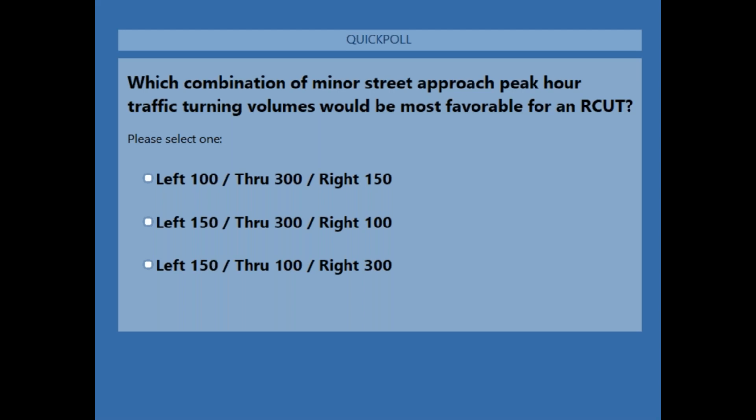So for example, and again, if we're dealing with a slow moving piece of farm equipment, unlike a vehicle or a car that can quickly accelerate, this slow moving piece of equipment, you really don't even want it on the roadway. So by pulling the U-turn bay all the way back, when there's a sufficient gap for the farm equipment to clear the two lanes of traffic, they basically are able to get into the turn bay or the lane that leads up to the turn bay. And so they can continue slowly to the U-turn bay, get to the U-turn bay, wait for another gap.